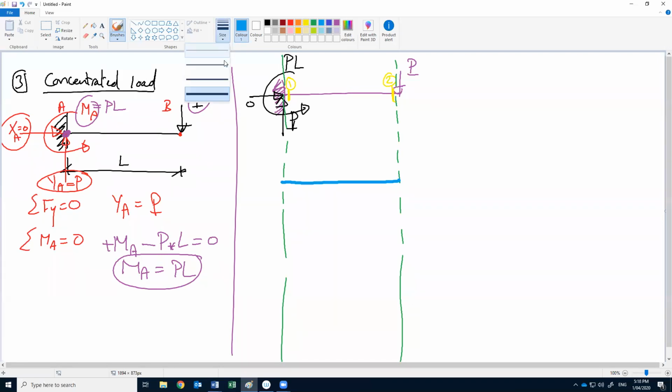So with this as our datum, what is the shear force diagram here? With the same procedure, what causes shear at 1? The reaction force B, upward or downward? Upward. So we have B upward here. From 1 to 2, we don't have any forces, so the shear should be straight, constant, B, right? After 2, we have this force downward, so it goes to 0.